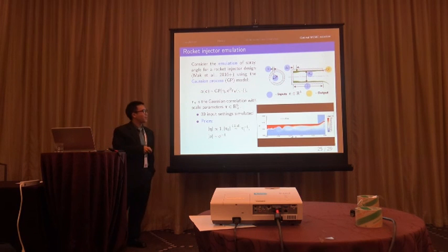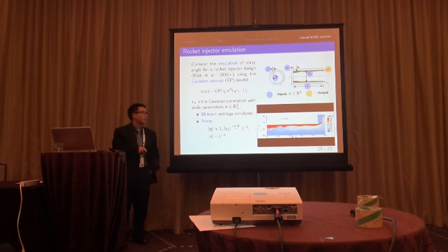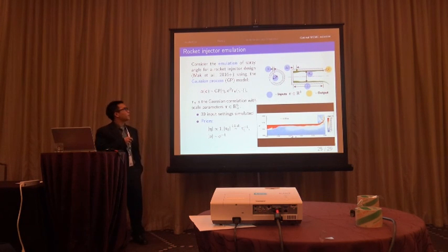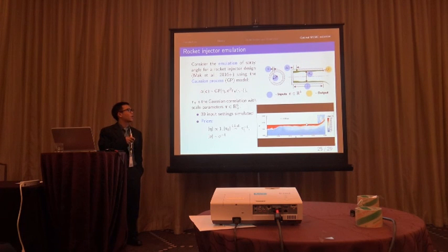Right. So this is the simulation that's spit out by solving the Navier-Stokes coupled with a lot of different things, right? This is time, spatial temporal flow. And what we're interested in here is a bit of a simple case, just for illustration. We're interested in the time averaged angle, time average response as a function of the input space. And we're going to build an emulator using the Gaussian process as well, with the process mean, process variance, and the correlation functions, right? So that's that.